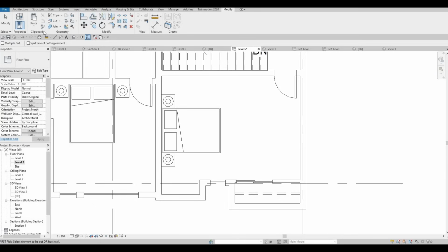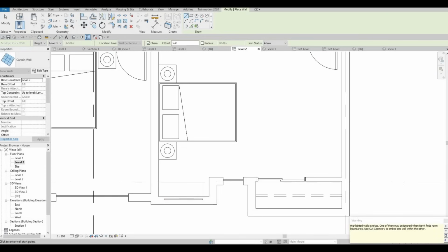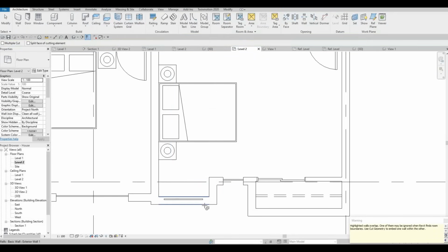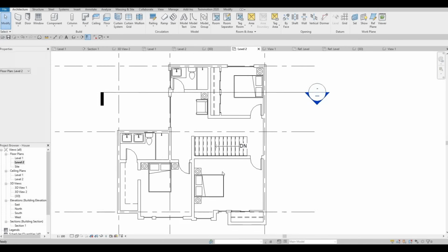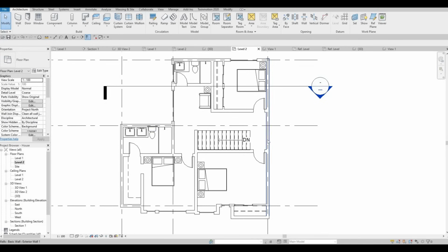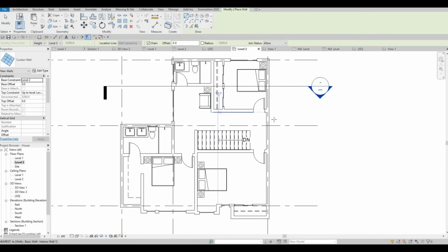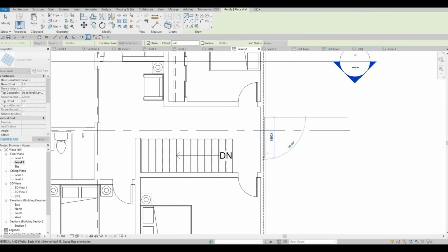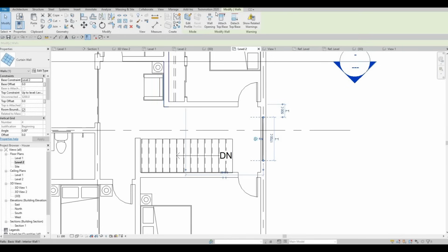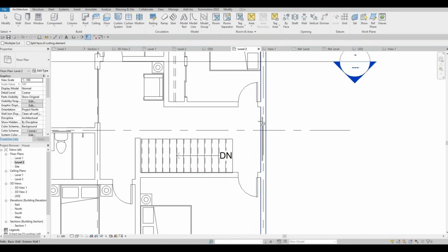We have a little nook here and we could just add a table and a chair, a study table here and a chair. So let's add one right here and then make sure to use cut geometry. Now that it's done, we could also add a window right here. I think that will be beneficial so that there's natural light going inside. So let me add that quickly and flip it and then go and cut geometry.